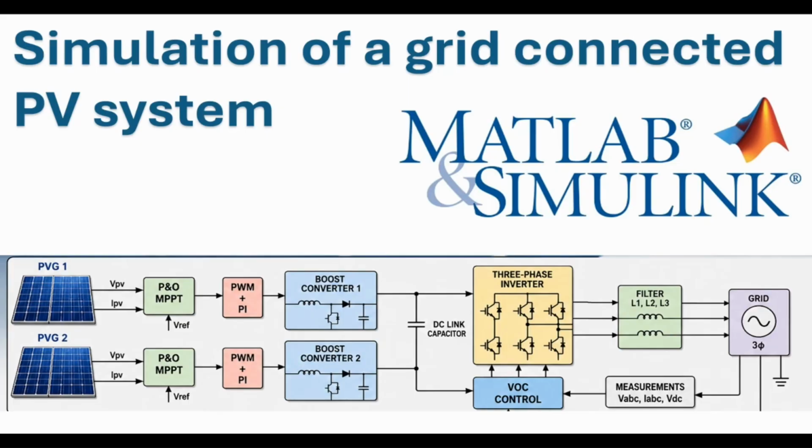Instead of forcing all the panels to share a single operating point, each string gets its own DC to DC boost converter and its own maximum power point tracking loop. All of these converters then feed a shared DC link, which powers a single grid-connected inverter.